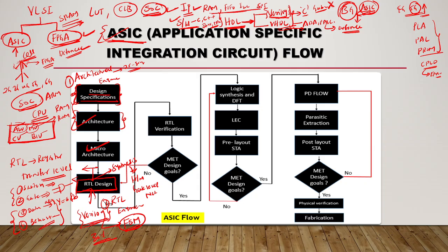If you want to do verification, verification is nothing but checking the correctness of your design, whether your design is correct or not. For that verification you need RTL verification. In this you use SystemVerilog and UVM. SV is also used.